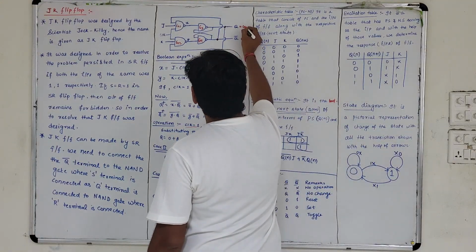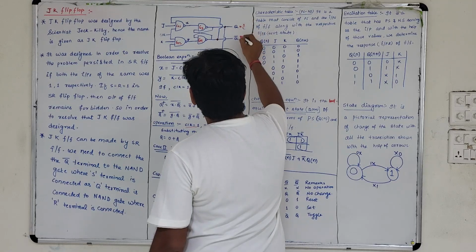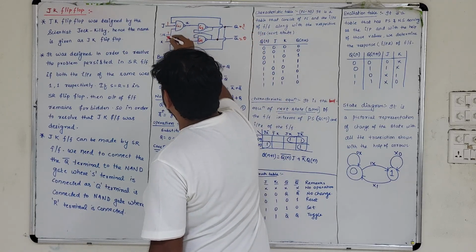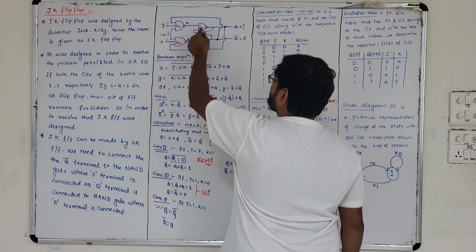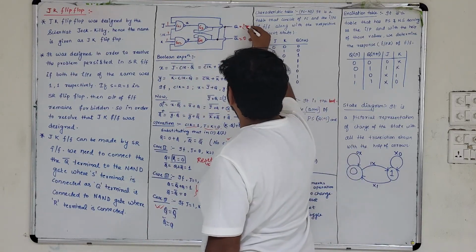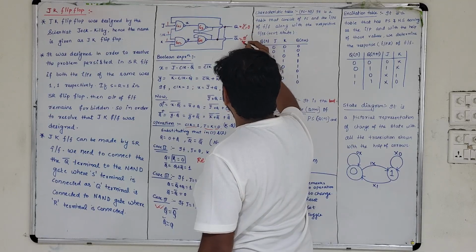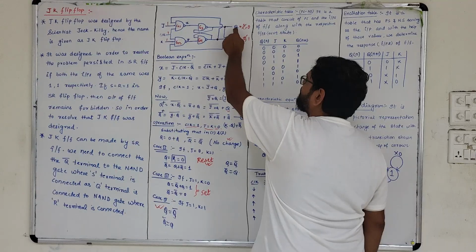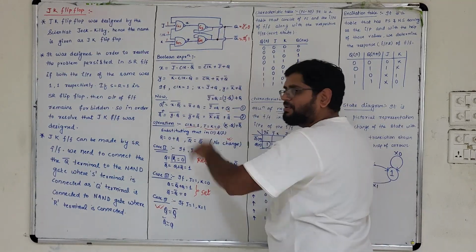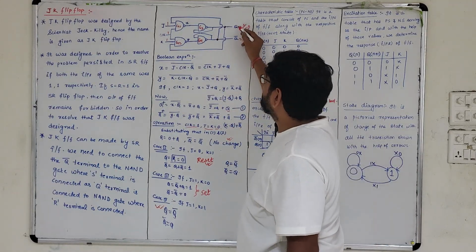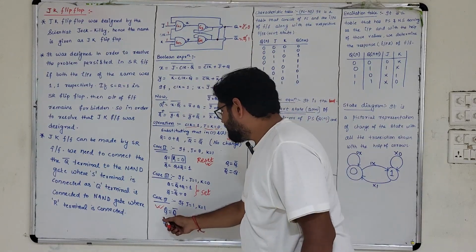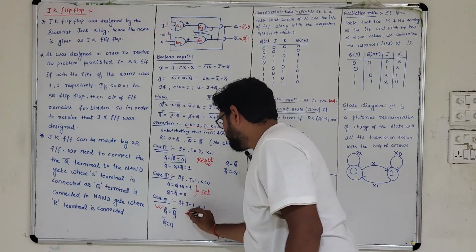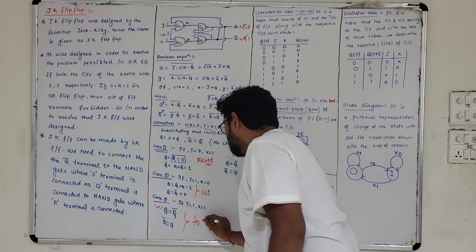So in order to understand this state, you need to go for the normal analysis method. You need to take this value as 0, this value as 1, or this value as 0, and then keep J equals 1, K equals 1, and clock equals 1. If you go for a normal analysis, you will find that this Q value comes out to be 0 and this Q bar value comes out to be 1. That states that whatever value you kept previously, it is coming as the complement of that one. That means it is nothing but Q bar and this will be Q. So for that reason, I have written here Q will be equal to Q bar and Q bar equal to Q. And this condition is described as the toggle state.